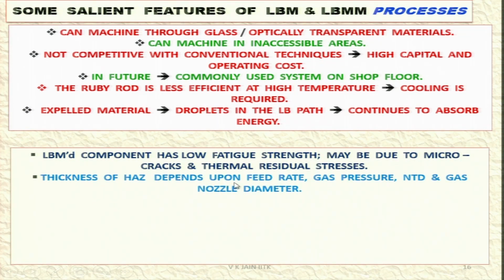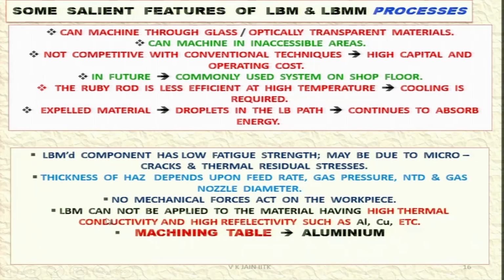Thickness of heat affected zone depends upon feed rate, gas pressure, nozzle tip distance, and TD means nozzle tip distance, and gas nozzle diameter. No mechanical forces act on the workpiece, we have already seen. LBM cannot be applied to material having high thermal conductivity and high reflectivity.